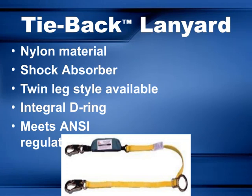Let's take a closer look at some key features of this fall protection equipment. First, the nylon material used here is known for its durability and strength, making it reliable in demanding work environments. The shock absorber is an essential safety component that helps reduce the impact force during a fall, providing added protection. This model also offers a twin leg style option, which can give you more mobility and flexibility, especially when working across extended areas.